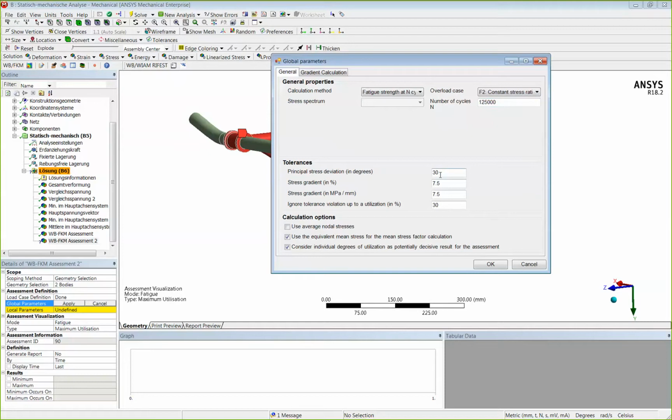And when we do that with an FEA calculation, we will see it's relatively true, not absolutely. So we need some tolerance here, and the tool automatically checks if we are above or below this tolerance. When we are above it, it will give an error message, and when we are below, it will simply give us the result.